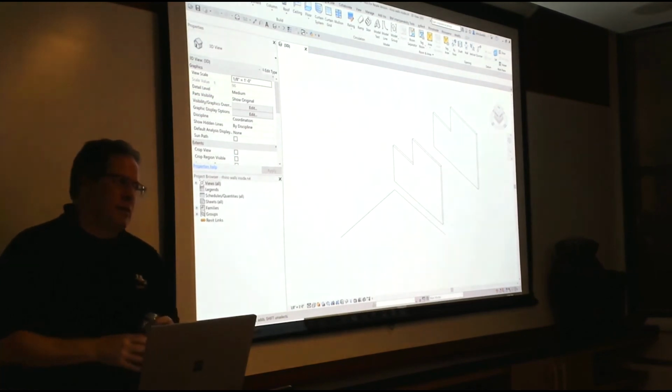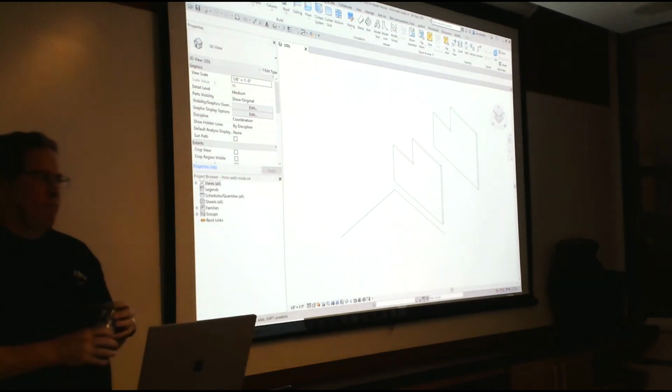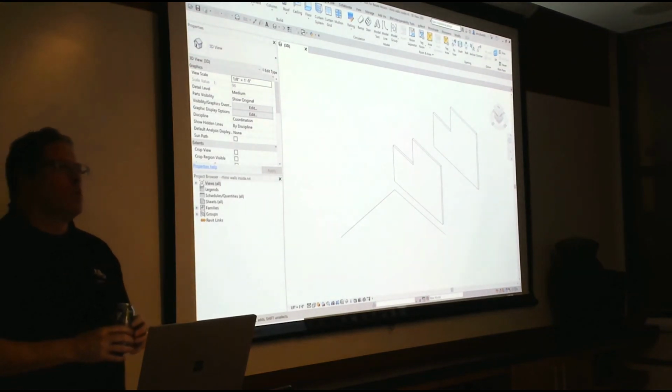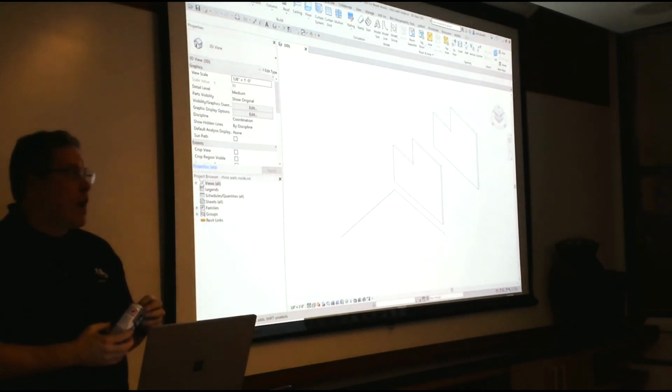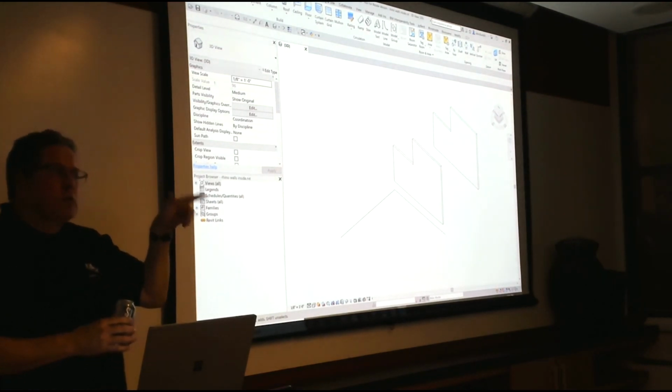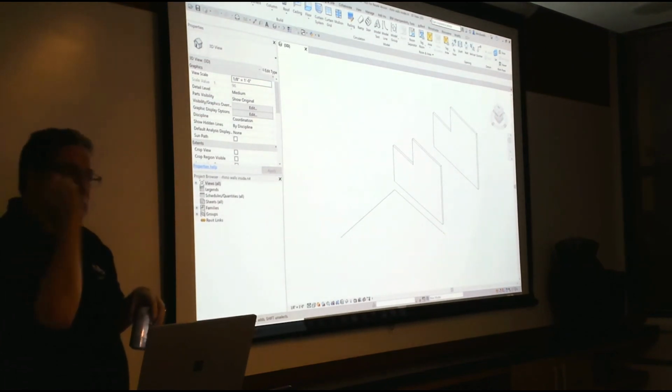So what we saw today isn't a product of just the model being so simple. It's a product of just the fact that Grasshopper is much better and Rhino is much faster at geometry calculations, yes. The only thing I would say is, on some big models, you have to hide the geometry in Grasshopper so you don't expose the whole building facade. Right, you don't want to, because then it instantiates all the objects. It becomes really heavy. You've got to be careful. You want Rhino to be doing the calculation and pop it into Revit.